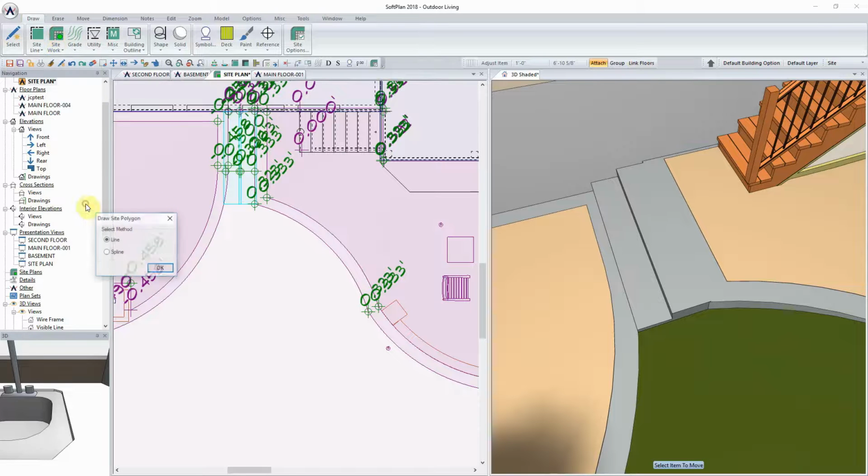Now the planting bed at this point, as I begin to sketch it in, I'll have the option of both line and spline. And I'm going to use the line and trace very angular type shapes to begin with, and then in time I'll come back and modify to set up certain lines to mimic or adhere to the same radius as the curbs that we're running this up against. And so when I select the line option, I'll just simply position my cursor where I want to begin, which will be where the stair meets with the curb, and click. And then I'll move my cursor left to right and click. At this point, I can hit the F12 function key to turn off the full ortho snap and move into 15-degree increments, and then click.